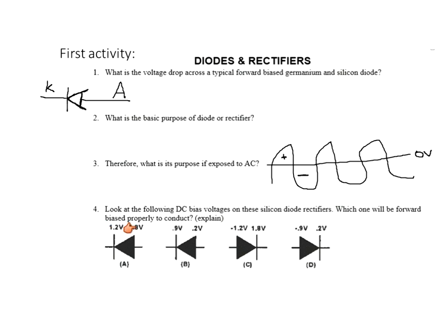Well, look at these voltages here of these different diodes. Which one of these has a higher voltage on the anode? Well, first you need to know, here's the anode here, here's the anode here, here, and here. This is the cathode. Here's a cathode, cathode here. To be forward biased, the voltage on the anode has to be a higher voltage. Well, let's see. Does this one have a higher voltage on the anode? It looks like it. This is about 0.6 volts higher than that one. So this possibly could be one.